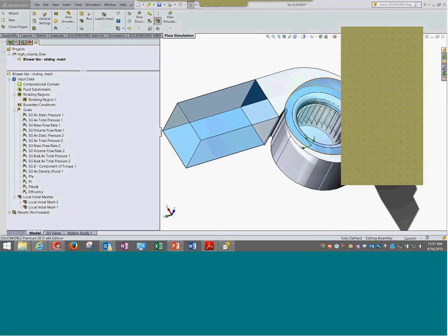Now the base results, if we take the velocity, the pressure or the densities, they are going abruptly high or abruptly low. The solver is not able to handle those scenarios. So it is difficult to say why you are facing that error. It could be many cases, and it could be file specific as well. So if you can, I would obviously like to discuss one-on-one on that particular file.